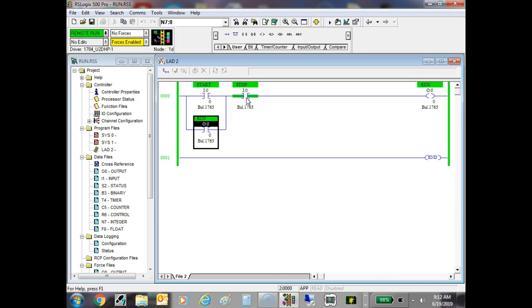You know, it always seems to me like there was a line going through that. It's like magic. Well, they're not changing the instruction. All they're doing is showing you when it's true. So if it's highlighted in green, it means it's true, right? If it's not highlighted with green, it means it's false. But normally over here we say these guys are energized or de-energized when technically they're not. So okay.